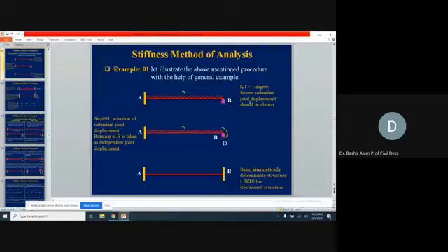So one redundant joint displacement should be chosen, and there's unknown joint displacement here. I show this on the second sketch, which is D. In the clockwise direction, we are taking this as positive. So this D is for the unknown joint displacement. As there is only one, with this general D I am representing. If we have so many, then we start labeling them by D1, D2, D3 up to as many as we have.